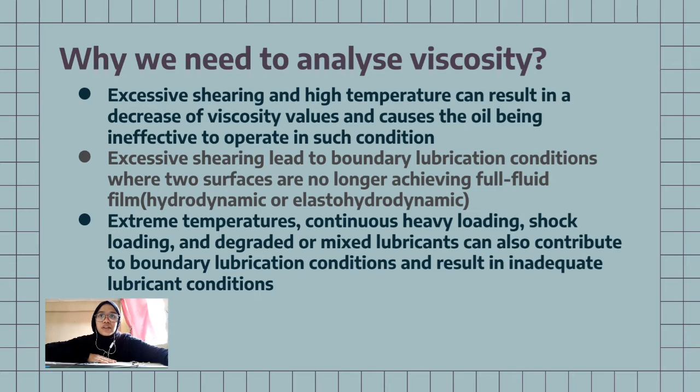These are several reasons why we need to analyze viscosity. First, excessive shearing and high temperature can result in a decrease of viscosity values and cause the oil to be ineffective in such conditions. Second, excessive shearing also leads to boundary lubrication conditions, where two surfaces no longer achieve a full fluid film, which is hydrodynamic and elastohydrodynamic.